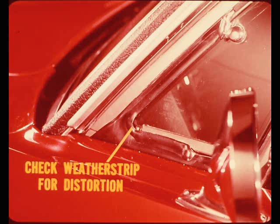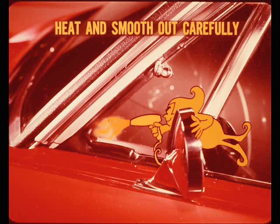On some cars, you can reshape the weather strip by softening it with a heat gun. When the material is pliable, smooth out the pucker carefully and work it into shape as it cools. The pucker may need a couple of treatments before it stays put.